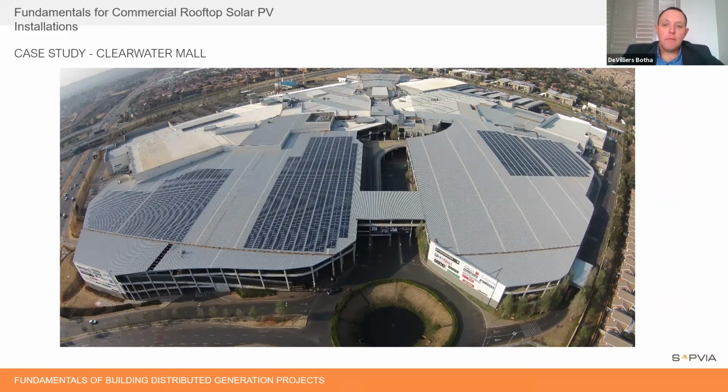We then switched on the system, and I'll get to the reason after these slides. The reason why a grid-tied solar PV system would work for them to expand their consumption was because the largest consumer in the mall is the air conditioning. And air conditioning works harder in the longer summer months, and that's also usually when you have quality sunshine, and then what we can call the air conditioning load match. So you didn't need a battery to expand that, all right?